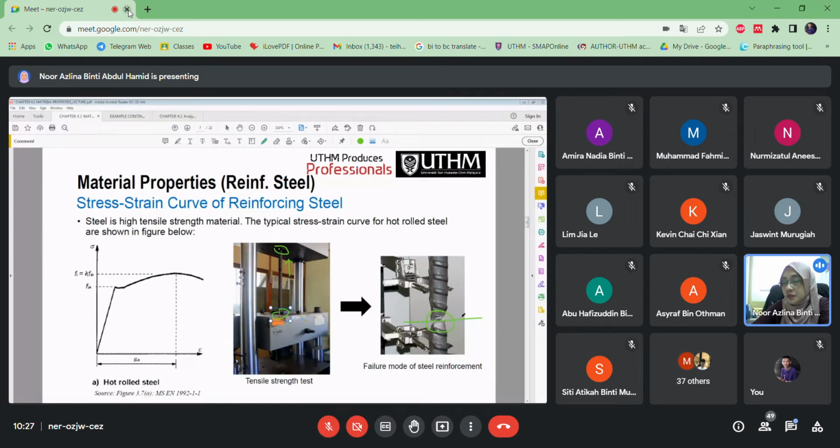There will be a necking here. If you look, you can see how the diameter of the bar decreases because of this tensile test. So the diameter here reduces, right? Until it splits into two here. So from the testing, we can come out with the maximum strength here. We will know the maximum until the steel fails here,